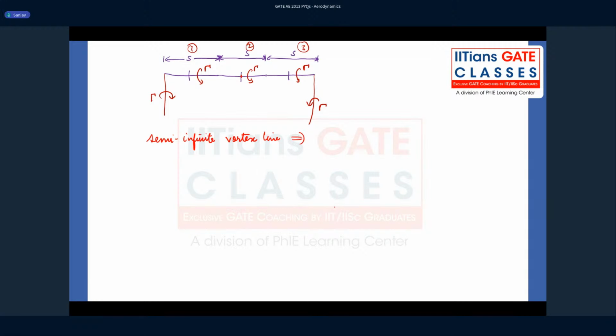The induced velocity due to this semi-infinite vortex line at a perpendicular distance h is minus gamma by 4 pi h, where h is the perpendicular distance from the vortex line to the point where you are finding the induced velocity. It is minus, but let's take the magnitude, so it's going to be plus.